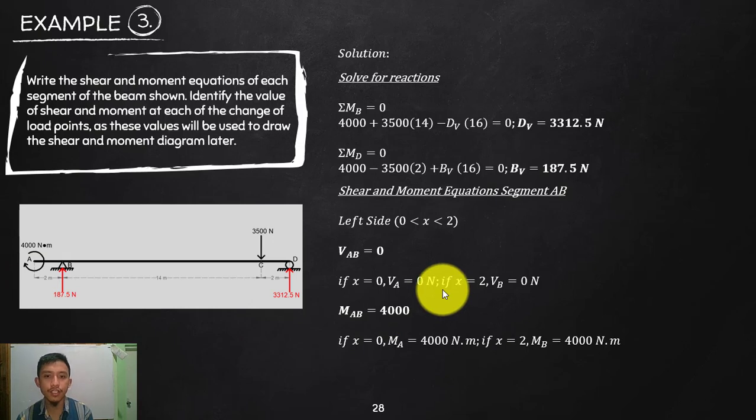Shear will only be because of the summation of forces. Your moment equation is now the summation of moments. Now you will establish your equation for moment, since that is already a moment, not a force with a certain distance. So there will be no distance multiplied with that moment.